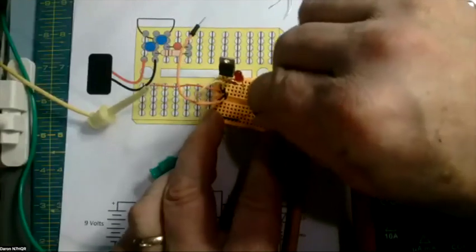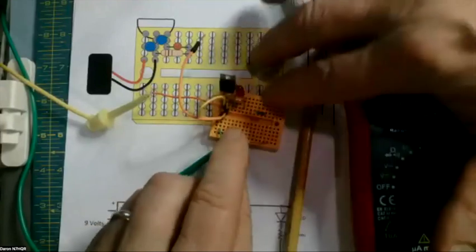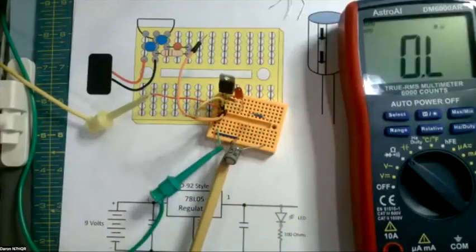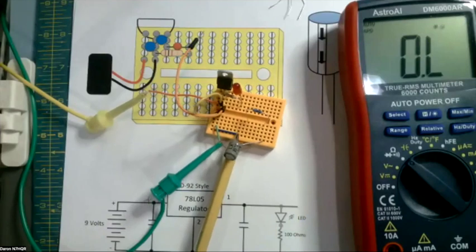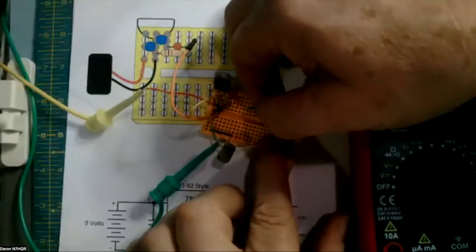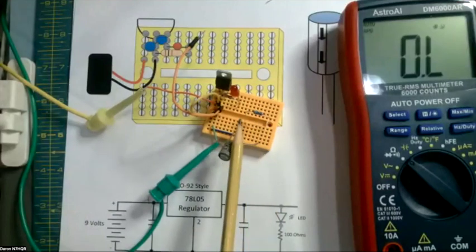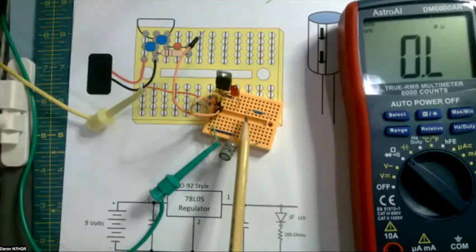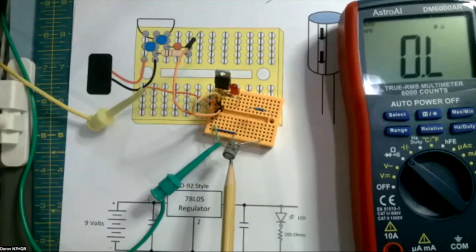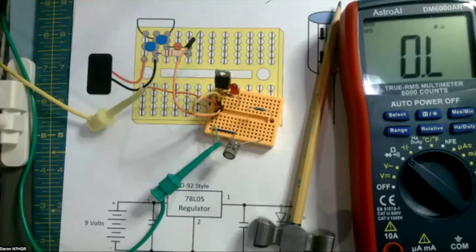Let's do, how about this? Okay, so now we just changed this a little bit. So the negative side of the capacitor is in the column here with the ground, right? There you go. We jump over here and I missed it by one. Then we're connected to the resistor and we'll apply plus 5 volts to this side of the resistor and power will go through the resistor and charge up the capacitor, right? Correct. Okay, do you want to meter that as we do it?